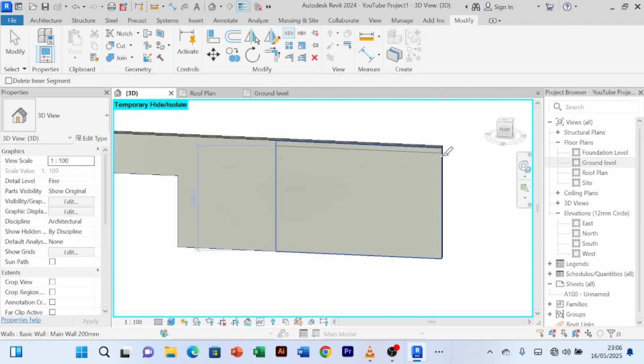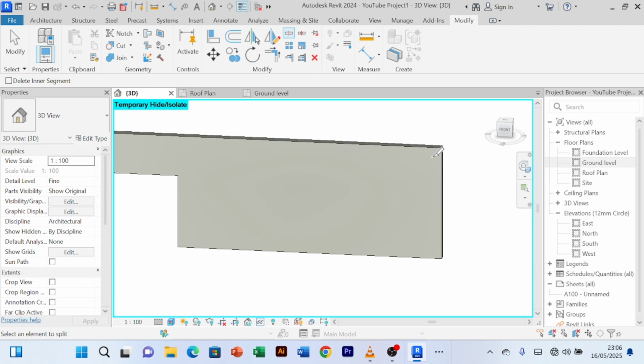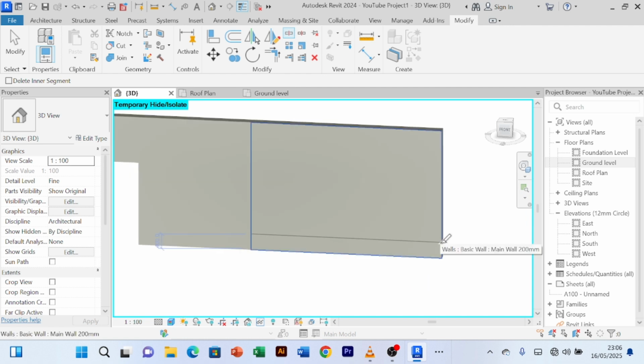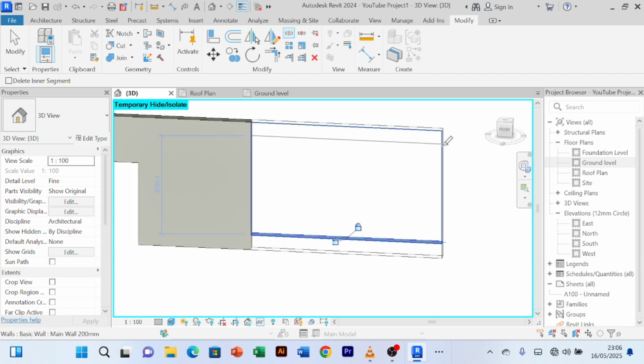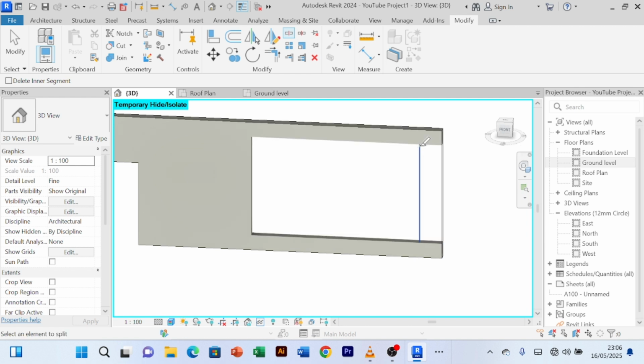For example, from up, these walls are, I think let me see the size, the height of the wall. Okay, down here we shall chop 400. Let's just chop 400 down. Then up we leave 2.7. And then of course this side we shall also have to give some wall. I'll chop here 600, then here 600.